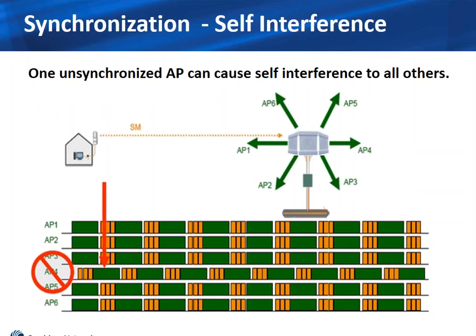So this is to show that it only takes one. It only takes one access point or co-located radio operating on a single structure to be out of sync to totally interfere with all the other access points. Don't get it in your mind that, hey, I'm using synchronization on 90% of the radios I have on the tower, and I only have one that's not synchronized. It's a different solution for whatever reason, and it can't be doing that much harm. It can, and this little visualization hopefully shows that.